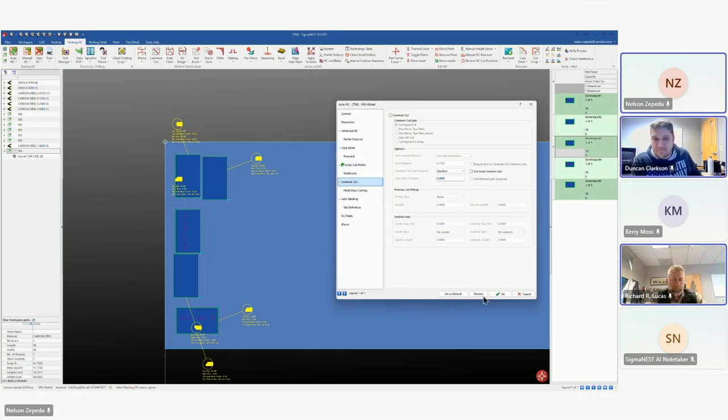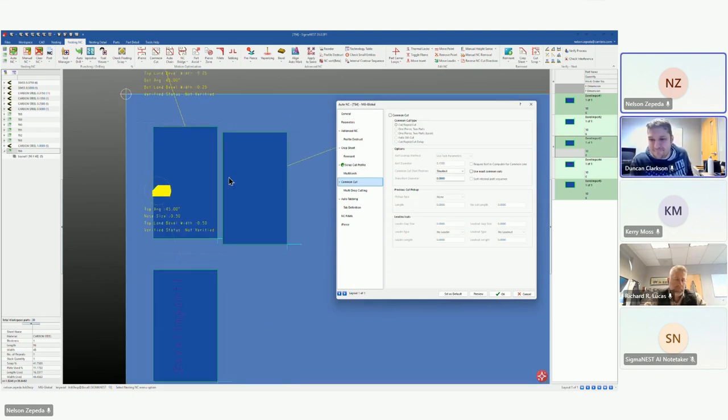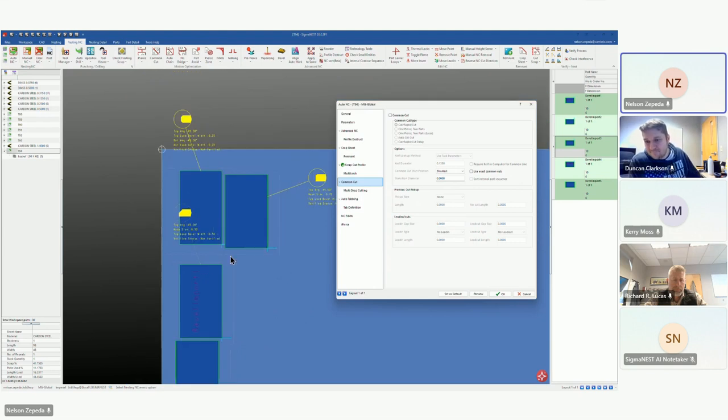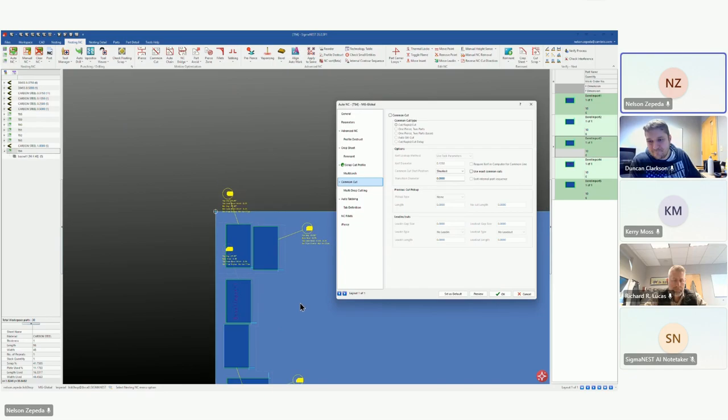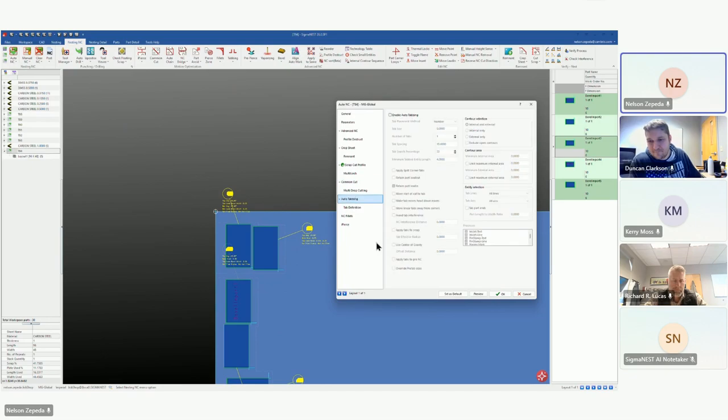We can also support common line cutting. This isn't a good example because these are bevel parts, but generally with your more square rectangular shapes, we could nest them in a way that they're going to share cuts, more often on lasers than plasmas, because on plasmas you'll have the one edge that's usually a lower quality, but we could do it for either machine. There's not a limitation in the software there.